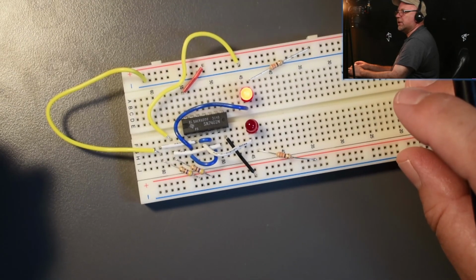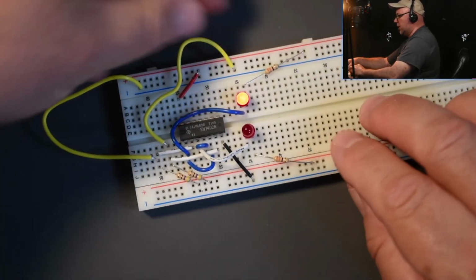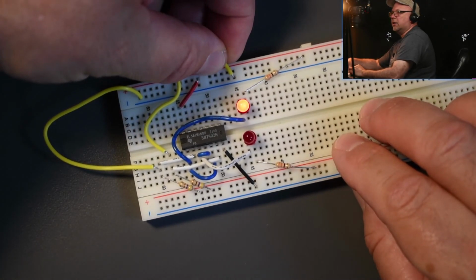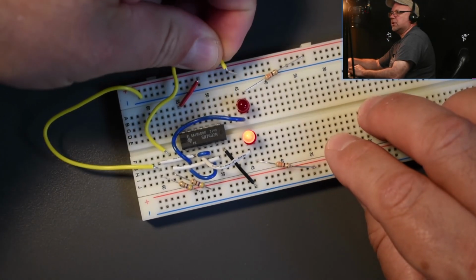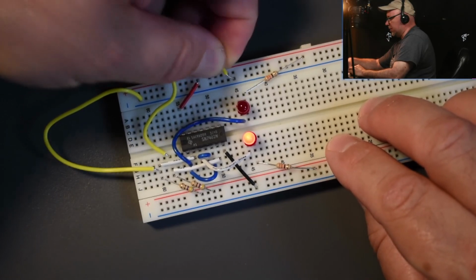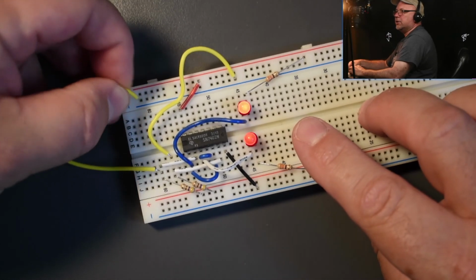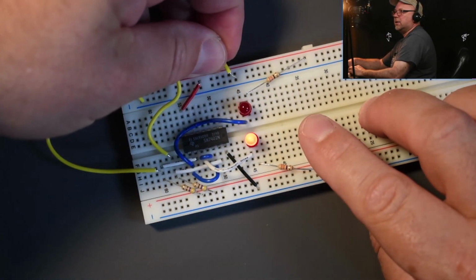Let's just leave it at the latched resting position here, and I'm going to do the other one, the reset. I'm going to momentarily make it high by removing the ground from that point, and this thing should switch. It does. Oh, look at that. It doesn't matter how many times I make it up and down, it stays going one way until the other input changes.